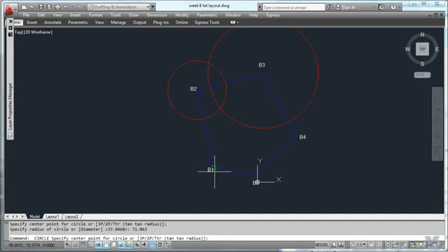We'll do that again. From down here for the other corner of the building, 40.896. And one last one from B5 is 51.616. So those two intersections are the corners of the building. So what I did is simulated taking a tape measure from B2 to that corner, B3 to that corner. Here, I think you can kind of picture what I'm doing.